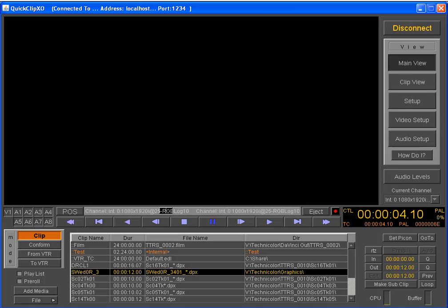When the DDR detects a problem, it flashes a code here. If I remove the video input to the DDR, the words IN and ODD flash in that space. This indicates there's a problem with the video input and the audio input. At this point, we only know that there is a problem and not the specific nature of the problem. In this case, the video input is missing, but it could also be set to the incorrect video standard.